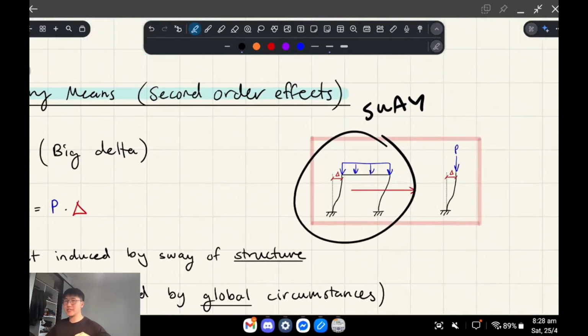So in the first case, the sway structure, right? Imagine my hands, the columns are here and here, and this is the beam. A sway frame, when it experiences, say, a sideways wind load, will basically get hit and it will sway like this, okay?